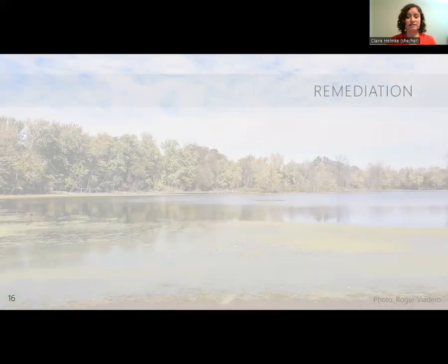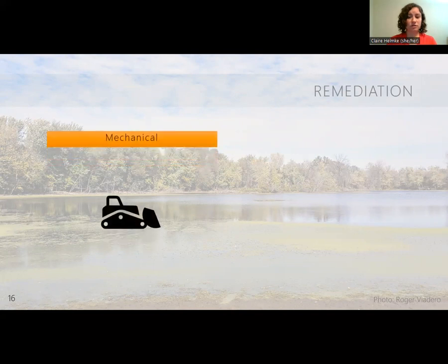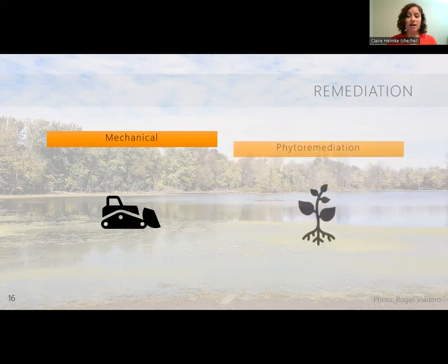Potential remediation techniques include mechanical sediment removal, which would involve draining Carp Lake and using machinery to physically vacuum up or bulldoze the sediment to remove it from the lake bed. However, with the high water table and how sludgy that sediment is, mechanical removal would be almost impossible. The machinery would be stuck or restricted to an arm length of an excavator positioned on shore. We would still be left with the issue of disposal of the sediment after removal.